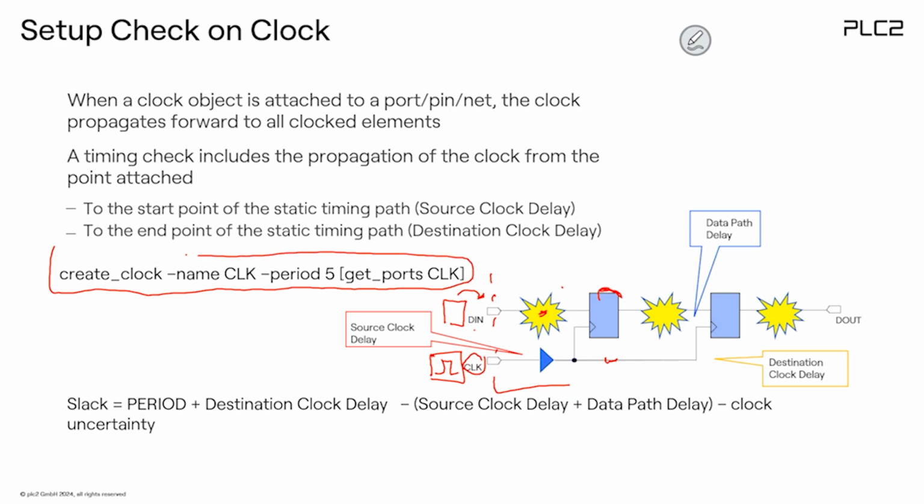The only thing you have to do is be responsible for defining the clock, and optionally define the timing behavior of the inputs. That's all you have to do. By using this definition, Vivado now understands exactly what the clock looks like. So in this case, a 5 nanosecond period.